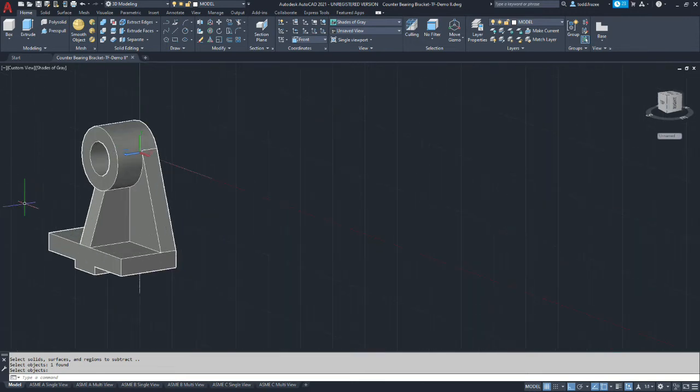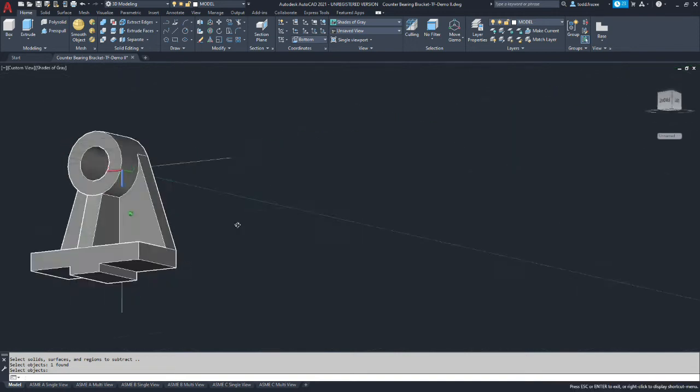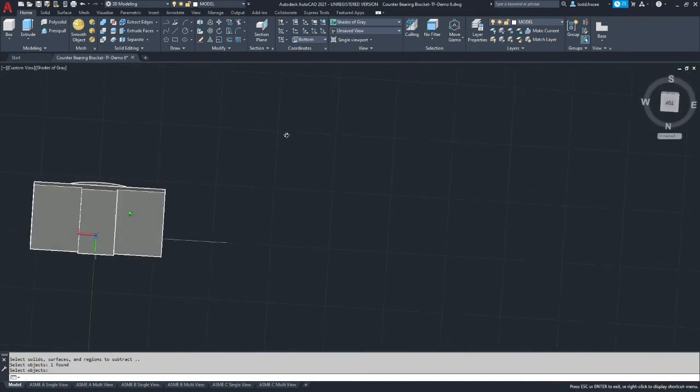Okay, so let's put in the bolt clearance holes. We now have all the additive work done. We're just going to finish off putting the hole features in. To do that, we are going to switch to the bottom plane. The reason I want to do that is it's a little less busy, and we can create the feature here on the bottom.